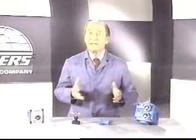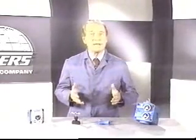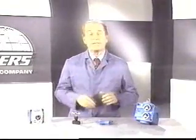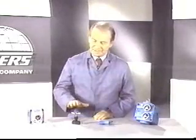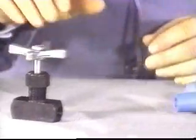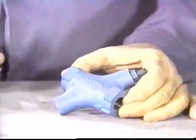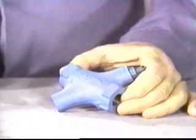So there are really 3 possible locations for the flow control. Where it's located is determined by the requirements of the particular application. Well, we've spent a lot of time on theory and schematics. Now, here's the actual hardware. Here again is our simple needle valve. This one's a non-compensated flow control. It's adjustable, and it has a check valve built into it for reverse free flow.